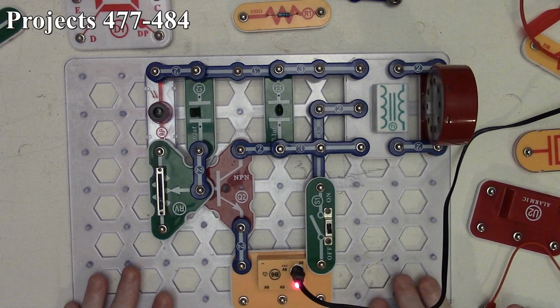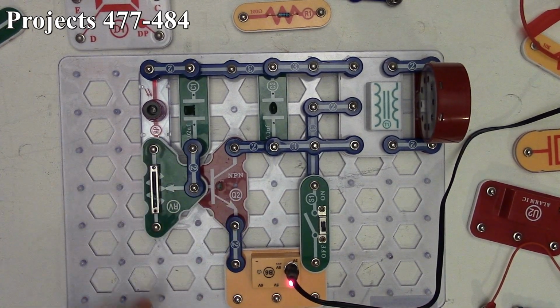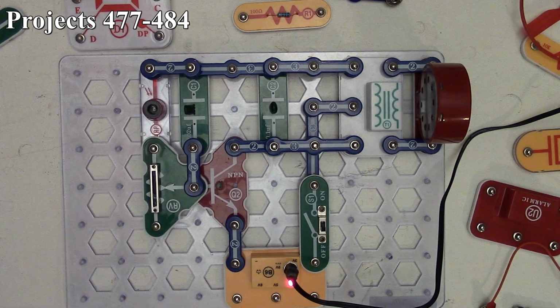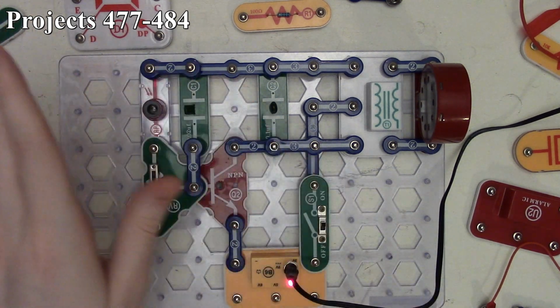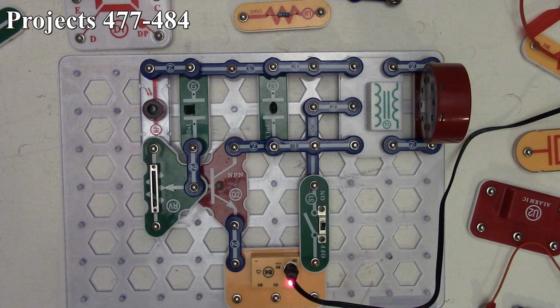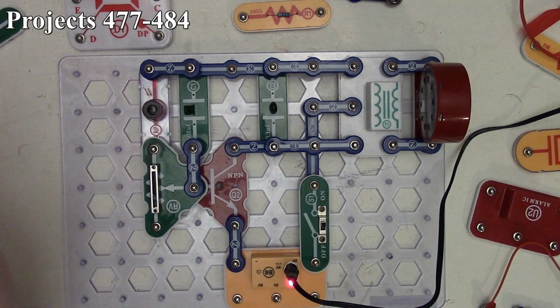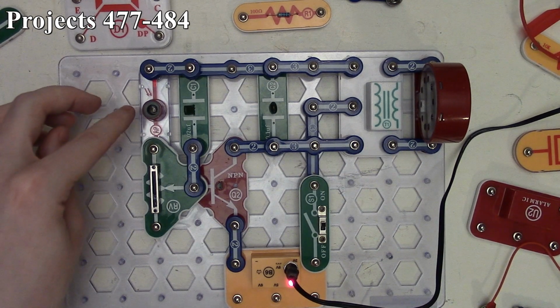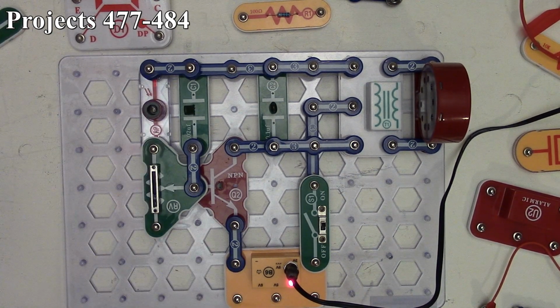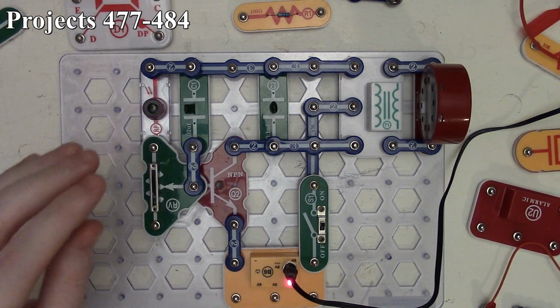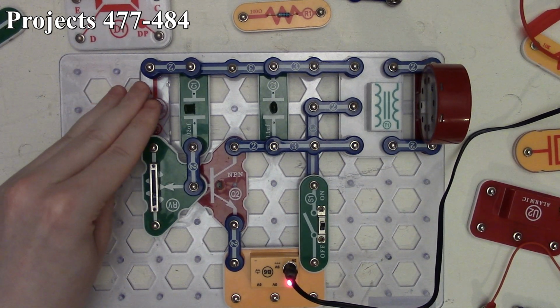And now by using the photoresistor, we can vary the resistance in two ways, both with our variable resistor here and with how much light goes into our photoresistor. So turn the circuit on. So already we get a different tone out based on the ambient light that we got going in there. And of course, waving my hand, putting a shadow over it already changes that. And of course, by decreasing the resistance there, it affects the base of our transistor there and slows down the oscillation of the circuit considerably.